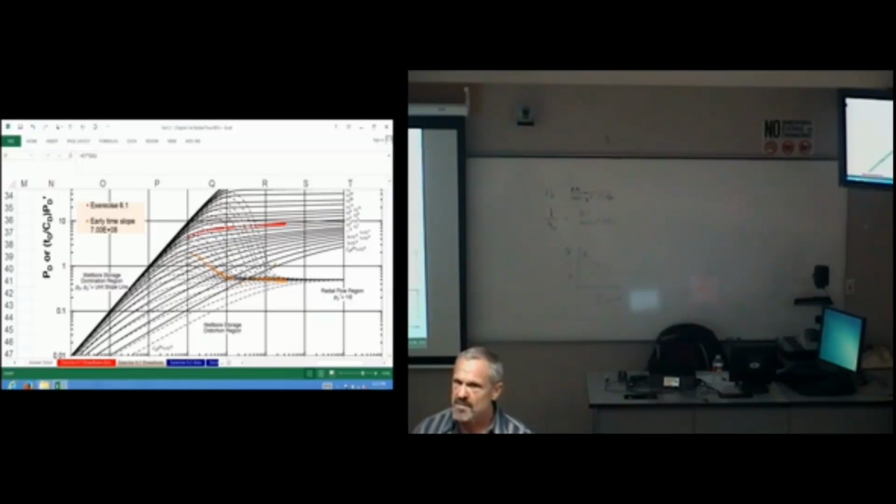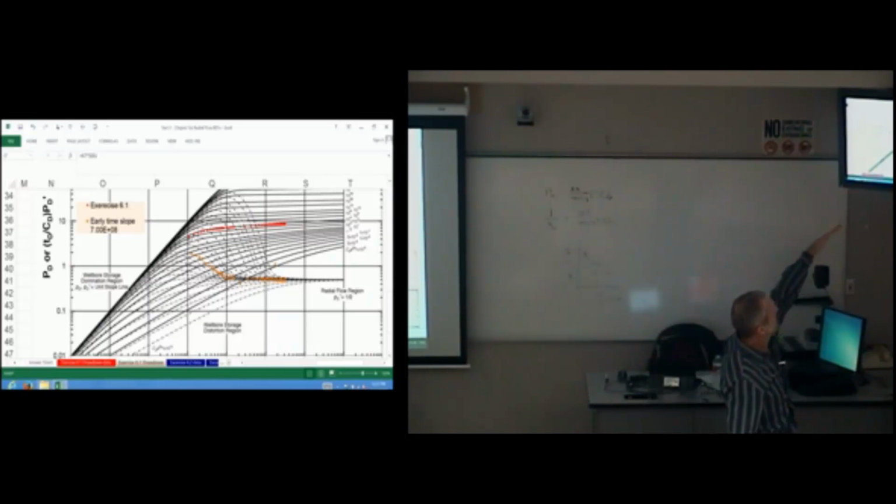So that's why it's not a moot point, even though it appears to be. I'm trying to train you up for type curves. You asked earlier what exactly I talked about: your early time slope. The early time slope would have been any data; we don't have it. It would be pressure versus time. If that's a straight line, then the log of delta pressure versus delta time will be unit slope on the log data, and that automatically gets us on our type curve.